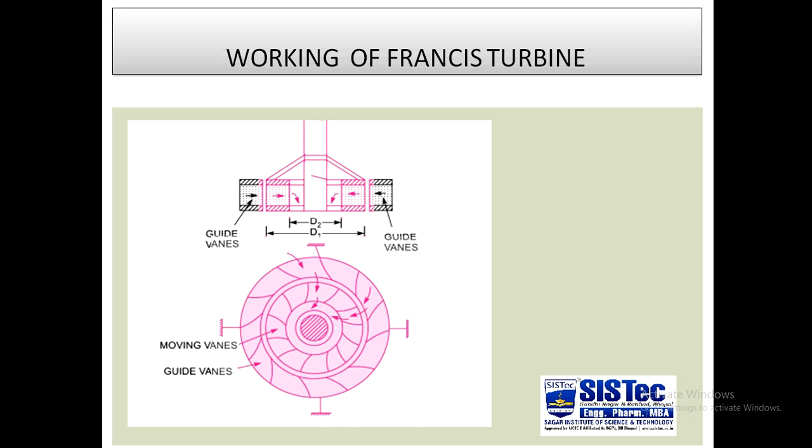In that, the hatched portion is the shaft which is used for energy transmission, and the outer circle, which is the last boundary of the plan, is your casing. The portion attached to the hatched shaft portion is our runner, and two types of blades or vanes are provided to the runner.